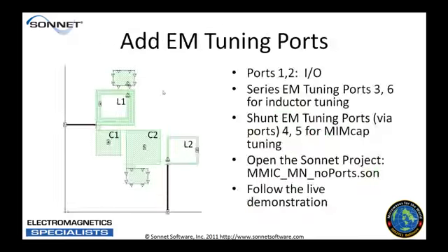Now, in each of these structures, we're going to introduce tuning ports, and that'll be the first step of the demonstration. Input port and output port 1 and 2. The series tuning ports will be ports 3 and 6, and our shunt tuning ports, which are going to be between the plates of our capacitors, ports 4 and 5. So let's take a look at it and pull it up in the Sonnet tool.